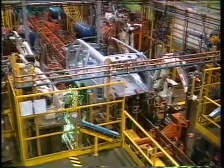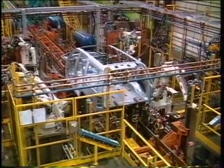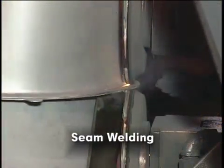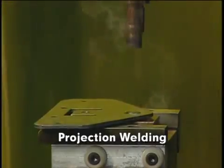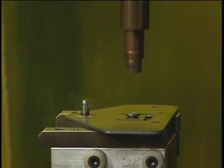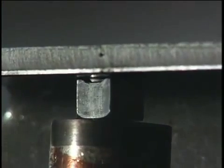Spot welding, with the electrodes maneuvered by articulated arm robots, is commonly used to join sheet components of automobiles. In seam welding, coordinated pulses of electric current from rotating wheel electrodes produce a series of overlapping spot welds, resulting in a leak-tight welded joint. In projection welding, the welds are localized at predetermined points by projections, embossments, or intersections. Several points may be welded simultaneously.